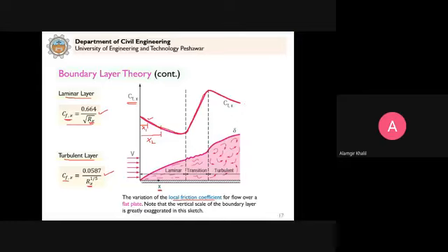But sometimes, for example, we have only this situation. Let's say this is the problem given to us, that we have only a laminar boundary layer, and for this you want to calculate the friction drag force. So then in that case, which CFx do you have to put? So instead of, you see it is variable, we just go for the average conditions. Clear?